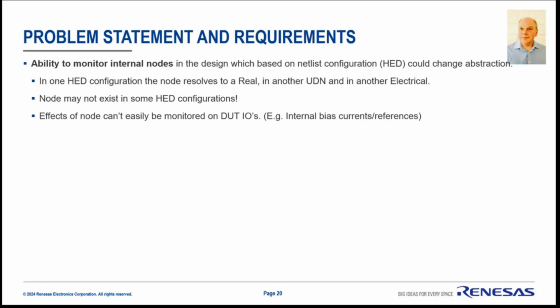But seeing that the kick happened is vital, because it's a verification hole that you don't know about. So being able to monitor it and say, hey, there's been a kick that shouldn't have happened, means we can trap things before they get into production. So we want to be able to monitor voltage, port currents, and power.